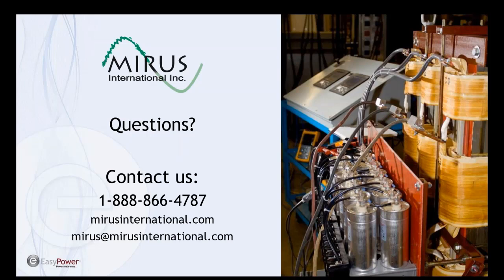So we don't normally recommend it. We wouldn't have a device that could be applied to an active front end drive. What we recommend is, when your requirement is simply low harmonics, there's no reason to put in an active front end drive. You're much better off to put in a simple 6-pulse drive and a good input filter. You're going to have a passive filter anyways.